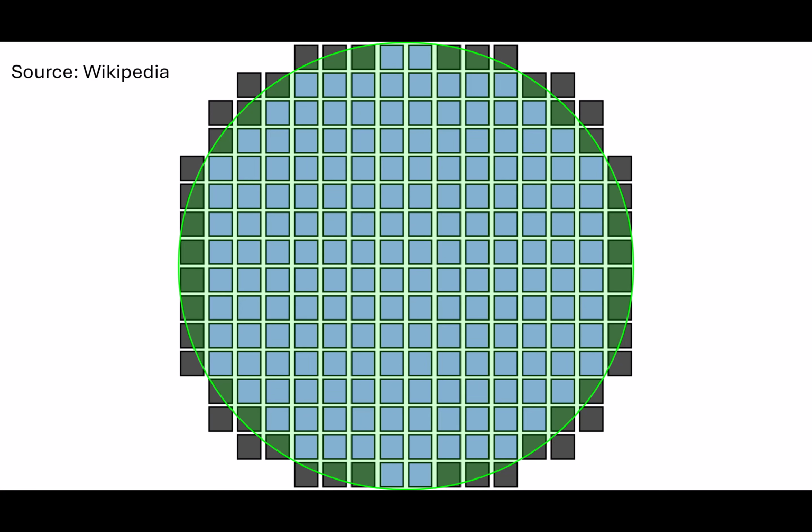Now, let us say I consider one chip in the wafer. In this one particular chip, let us say I had a resistor with a nominal value of 1 kilo ohm. Let us say I also have another resistor, identical dimensions, kept close to it. What is the expected value of this resistance? Ideally, what do you think it should be? 1 kilo ohm. But of course, as I already mentioned, no two things are identical, so there is going to be a mismatch. Here I have nicely drawn rectangular shapes, but in practice it is not possible to etch out rectangles, so we'll have some rugged geometry like this.